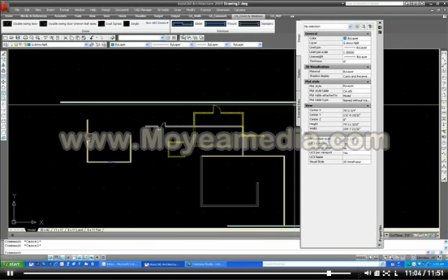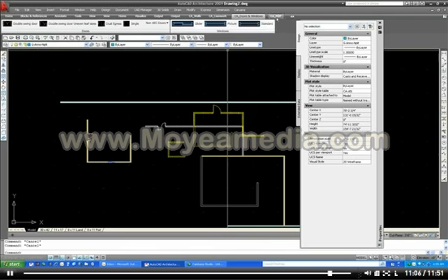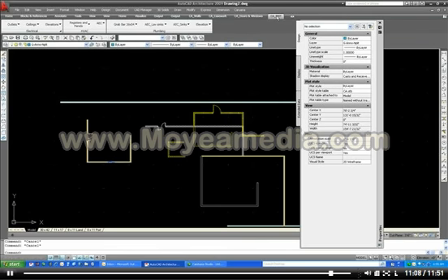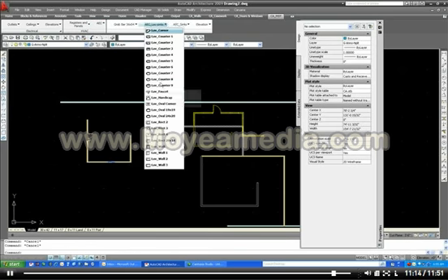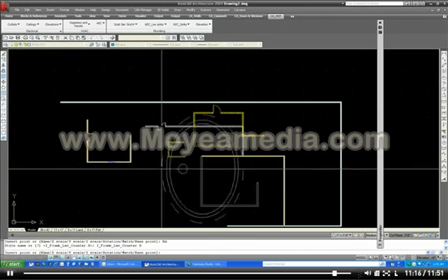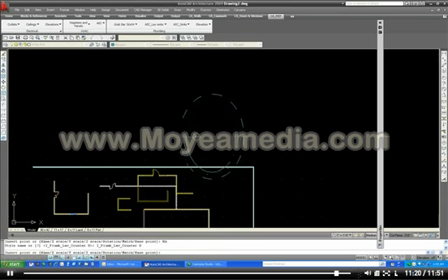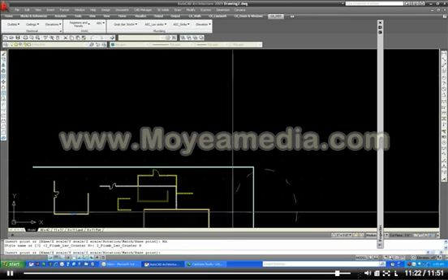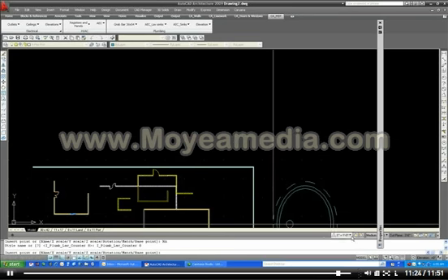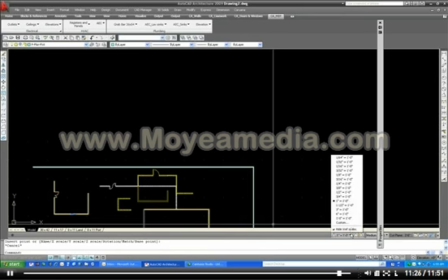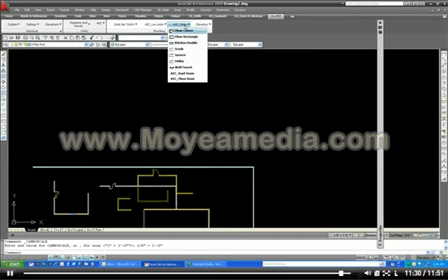So you can see a lot of advantages of designing with the pull downs and the tabs and panels. The tabs and panels are pretty quick, and you also got MEP stuff over here. So you can have some outlets, and you got like some sinks. Say you want to put a sink in here. You just need to make sure that the scale is correct. So like this one is kind of huge because it's drawn at 1 inch. So you need to change this over here to probably like 8 inch or something like that.